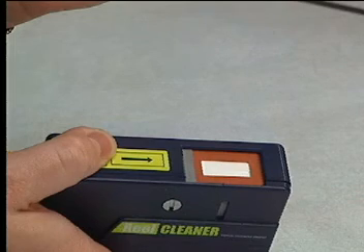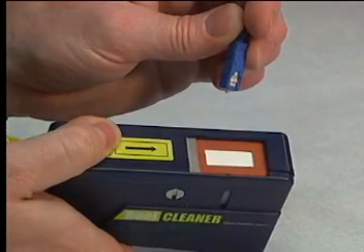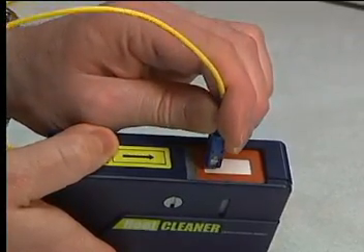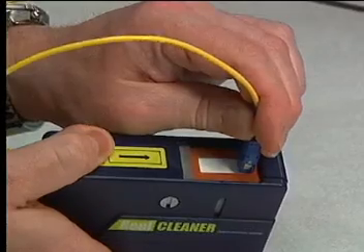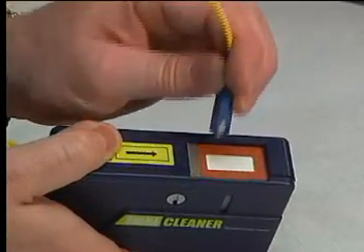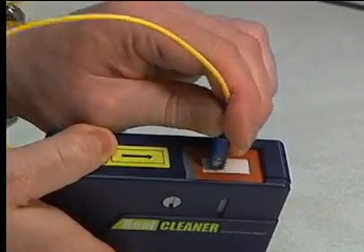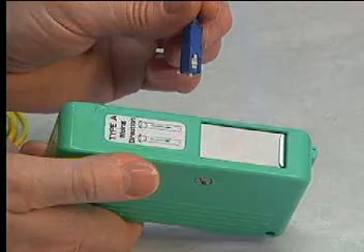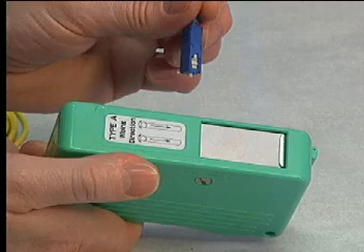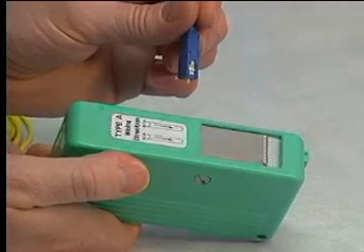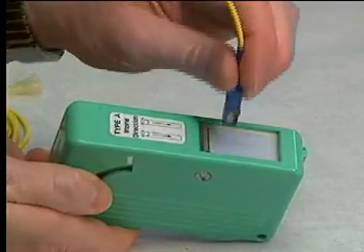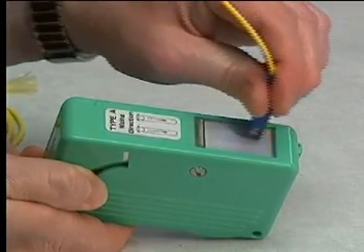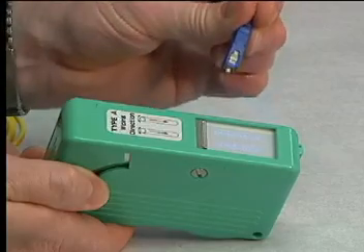The flap is retracted and the connector held in a vertical position. Lightly press the ferrule against the cleaning tape and slide it along the surface of the tape. The tape is wide enough to allow 2 passes of the ferrule over a fresh section of tape. This model of tape cleaner has 2 defined slots for the ferrule to pass through. Both slots must be used to ensure a clean ferrule end. When finished, the protective flap is closed on the cassette.